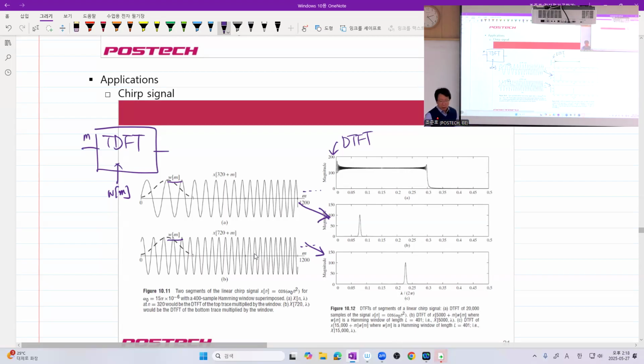The problem is that the function generates a complex number, and we usually love to plot the magnitude, so all the information about the order of the instantaneous frequency, so low frequency comes first, high frequency comes late, is lost. So that drawback is overcome by the time-dependent Fourier transform.